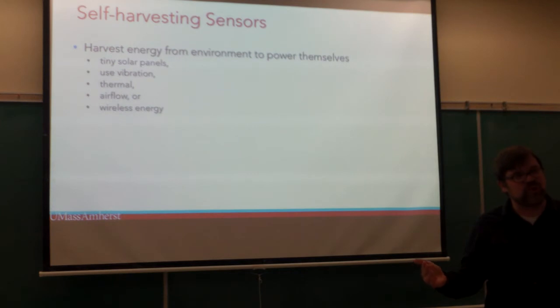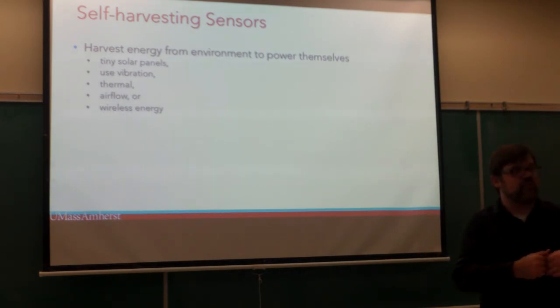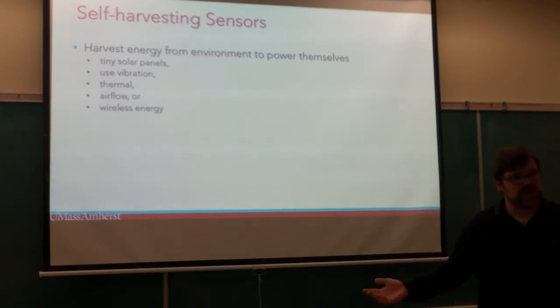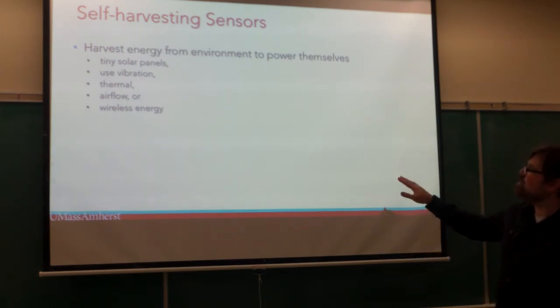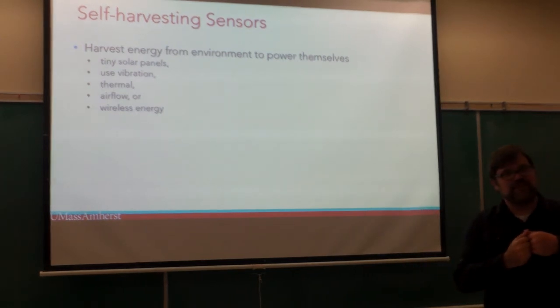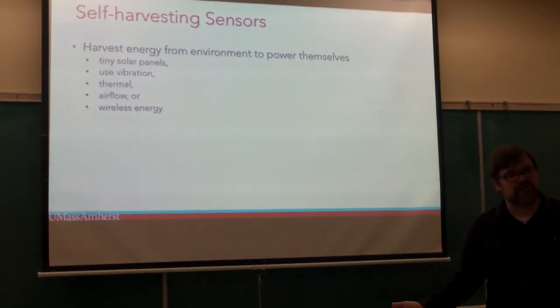For example, if you want to know temperature and you're powering your device from a temperature scavenging device, the rate at which you are sending packets implicitly says something about how much thermal energy there is in the environment. So in some cases, just by harvesting power on your sensor, you can do the sensing for free in the background.